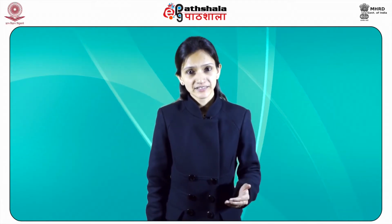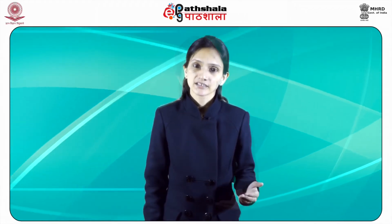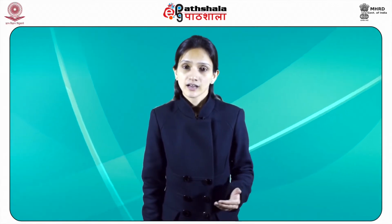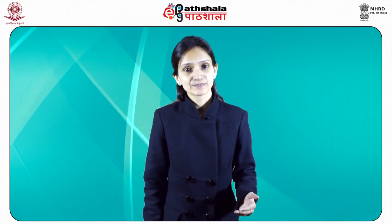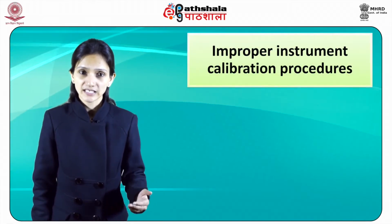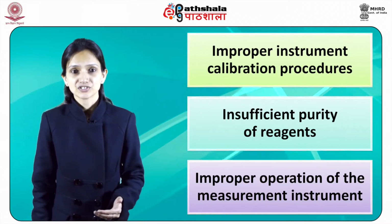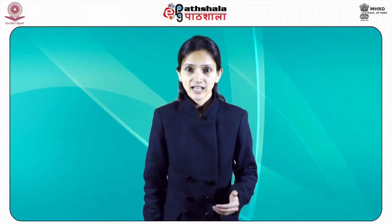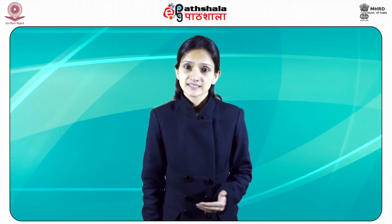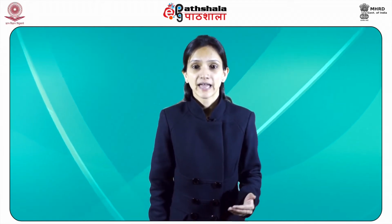The magnitude of the random error is usually small and can therefore be minimized by filtering methods, either hardware or software. The second kind of error, systematic or procedural error, causes results to deviate from the expected values in a constant manner. Sources include improper instrument calibration procedures, insufficient purity of reagents, and improper operation of the measurement instrument. This kind of error cannot be reduced by the application of statistical methods. Systematic errors may often be identified and minimized by modifying the analytical procedure.